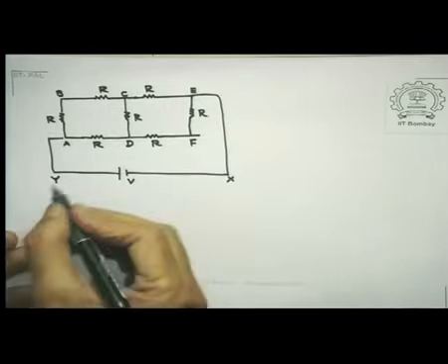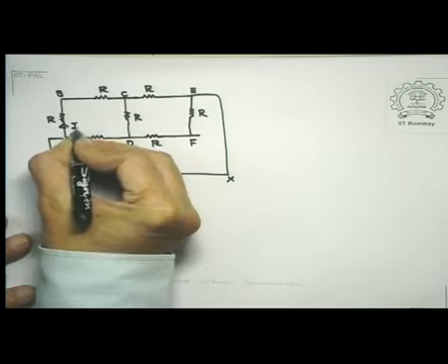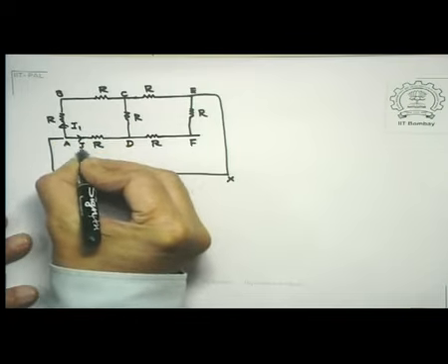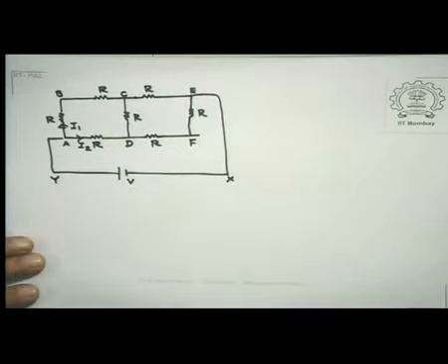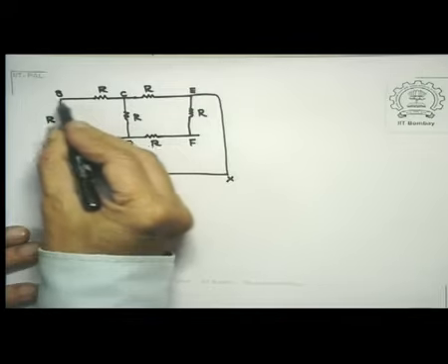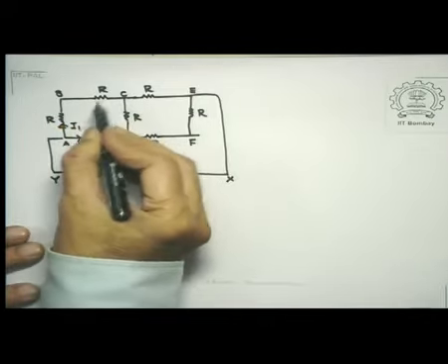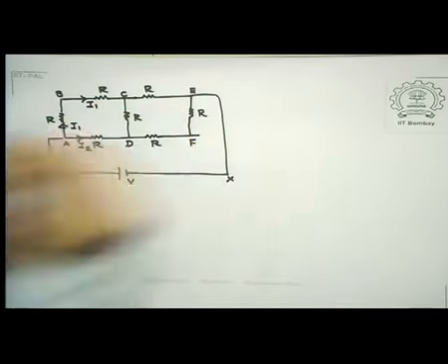Let's assume that at the point A, I have a current I1 going on this branch and a current I2 going on this branch. Now by symmetry, I know that this and this side also must have I1 and I2. Only thing is we have to decide which one should be having I1 and which branch should be having I2. Now in order to do that, you notice the following, that this branch which is having I1 is in series with this branch BC. So therefore, the current I1 flows through two resistances here.